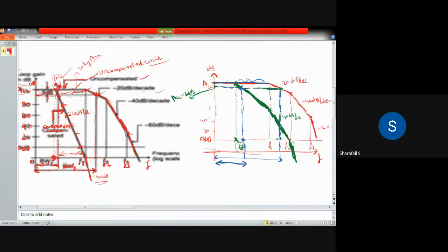Okay. So if it is having a phase shift of, for example, 180 degrees in this region, and we also have a gain which is larger and A beta is equal to 1, somewhat similar to that, then you will be having some oscillatory effect at the output.